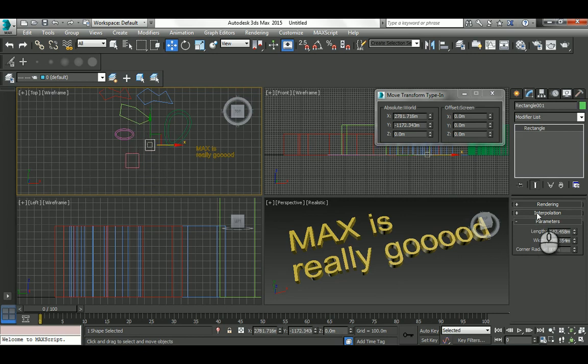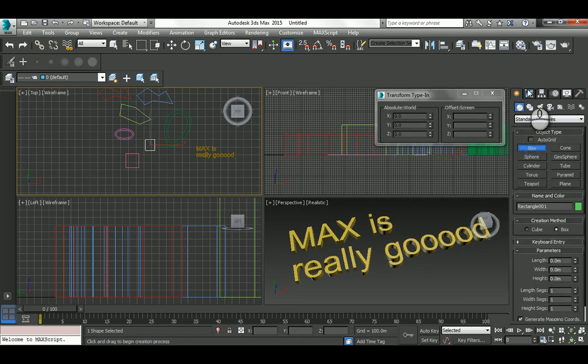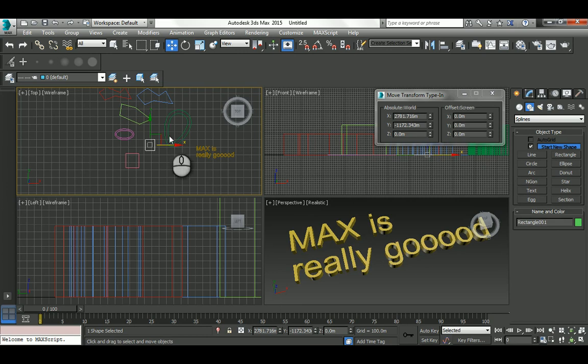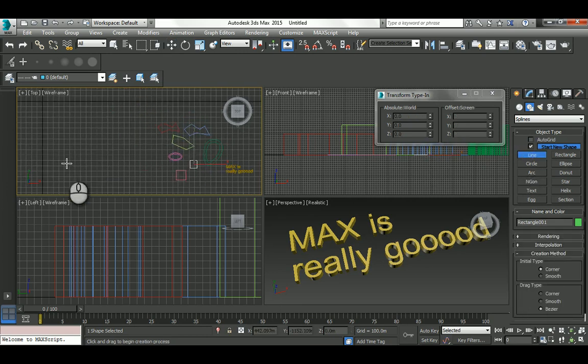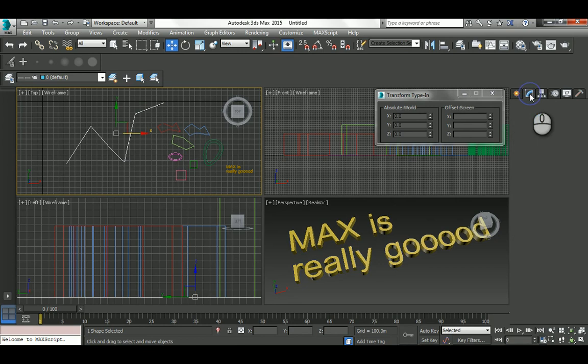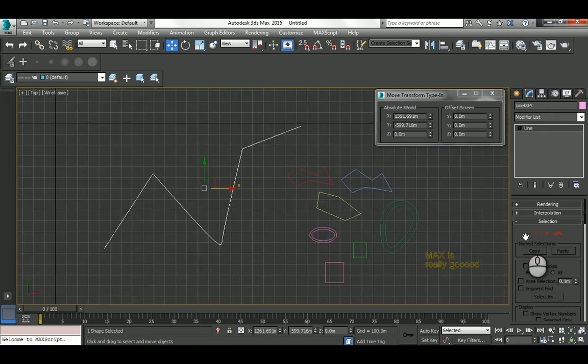Same thing we have with the 3D shapes, because when you create, you have those parameters, and when you go to the modifier after the creation, you get the same. Notice that that's not true for the line specifically, for some of them. So it doesn't have those settings. Okay, when you go to modify, voila, nothing. Because you're going to create those points, and Max allows you to click and create those relationships, but after that you're not going to change those relationships.